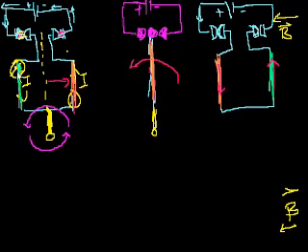Use your right-hand rule. The current is flowing down here, so if your magnetic field is coming to the left, then the net force is going to be down there, and it's going to be up there. And so we can continue indefinitely, and we solve our other problem, that we will never keep twisting these wires here. So now, using the commutator, we have essentially created an electric motor. And remember, I drew that little thing that could be like the axle, maybe that turns the wheels or something.